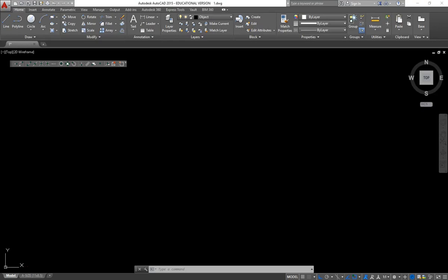To begin, I will draw the two views that were provided for us in the book, which is the top view and the right side view, and then I will use my construction lines to project over so that we can have a clear drawing for the front view, which is not provided. Now, before we begin, you will obviously have sketched this object on your sketch paper, so you already have a clear understanding of what the front view should look like.